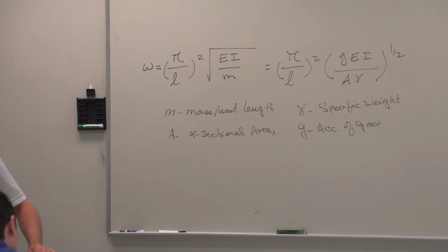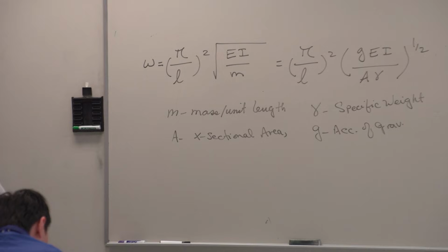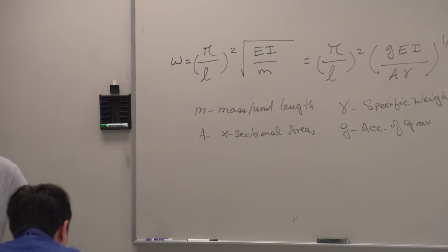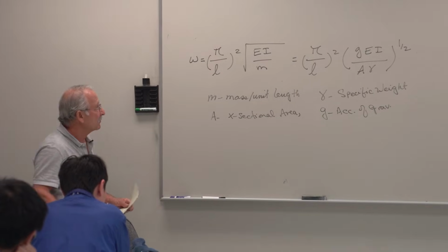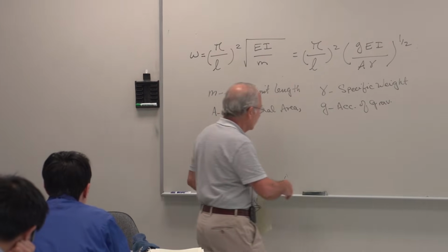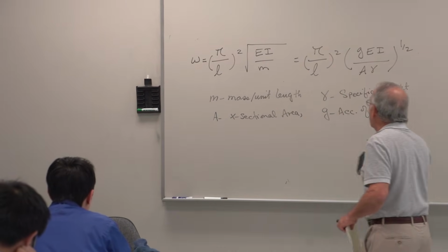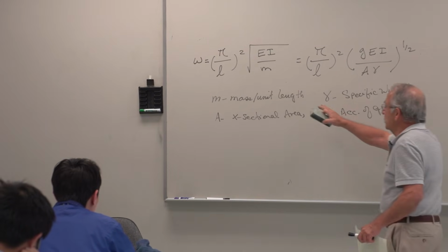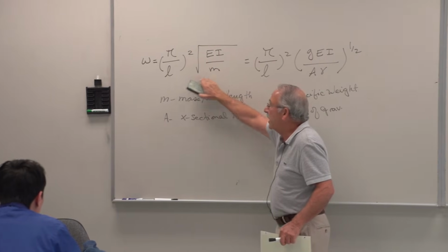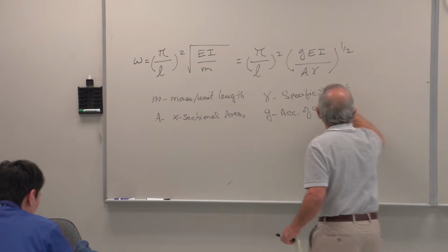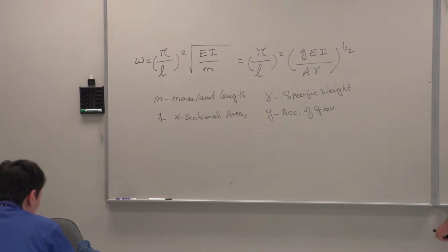So we calculate this. We know the frequency of the applied load. We make sure this is at least twice that to make sure that the shaft doesn't vibrate out of hand. And as you can see, you can decrease or increase the mass and change that, or I or E, all of those are possible.